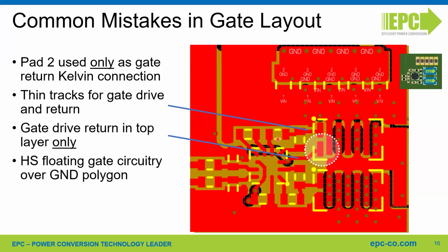So in AC, the ground is connected to the drain of the device, and this is adding Miller capacitance. Since our devices have gate to drain capacitance in the order of a few picofarads or even less, we have devices with 0.1, 0.2, 0.3 picofarad of gate to drain capacitance.